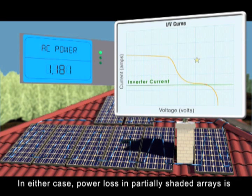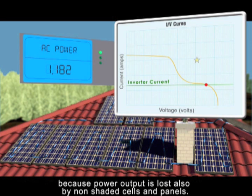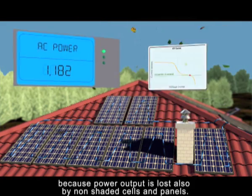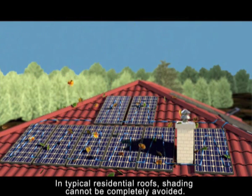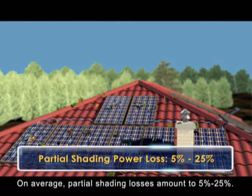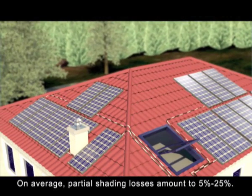In either case, power loss in partially shaded arrays is significantly greater than the reduction in the illuminated area, because power output is also lost by non-shaded cells and panels. In typical residential roofs, shading cannot be completely avoided. On average, partial shading losses amount to between 5 and 25%.